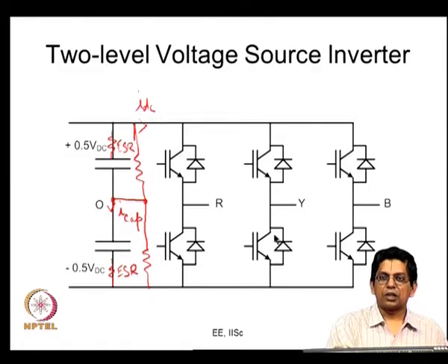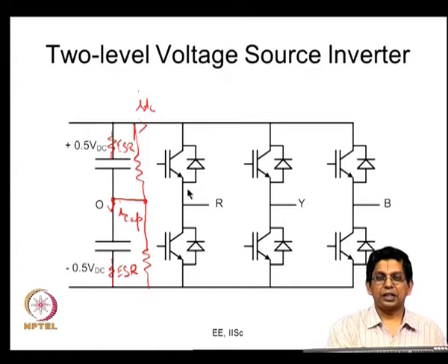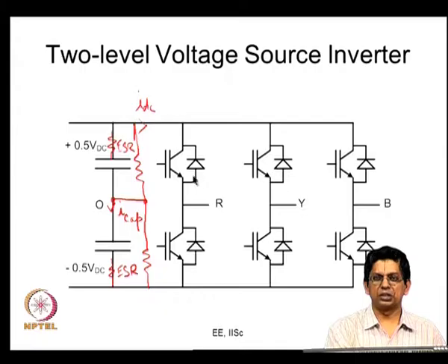The result of these losses is that there is going to be heating up of the junction temperature; the semiconductor inside would get heated up. If it gets heated up, it will not function okay. So, we have to have an arrangement for dissipating all this heat. What is normally done is you connect it on a heat sink. Every device is normally, you never use these kind of devices without putting them on heat sinks. So, you may have large heat sinks.